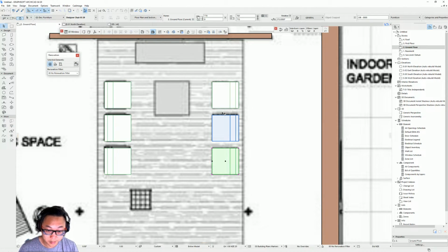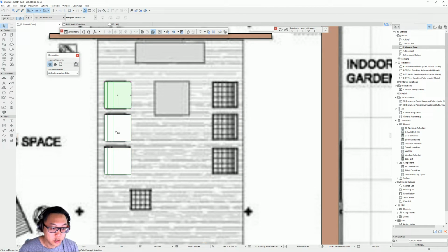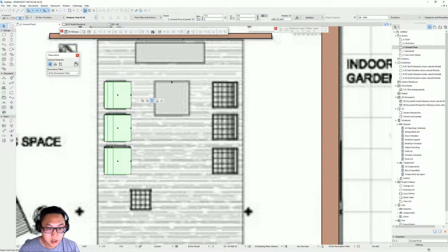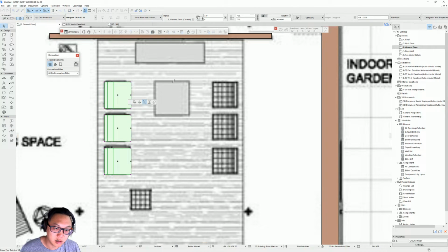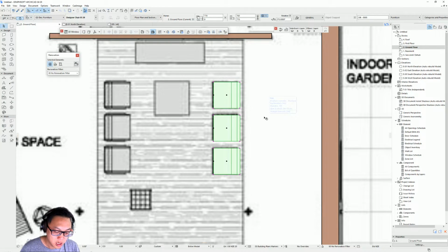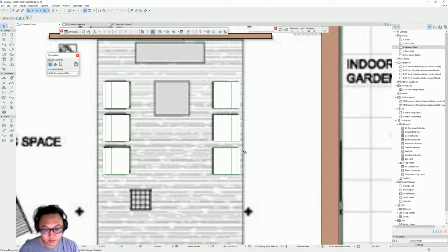The easiest way is actually you delete those, you select all the elements here, click on one point, and just use the mirror tool. And actually we have to place that table because the mirror tool is like I'll show you. Just press here, set the axis of the mirror, and now it flips on the other side. But then you want to actually have a copy, so I forgot to press Control. So you go mirror tool, select the axis. As you can see, there's no plus sign. So if I press Control, there's gonna have one plus sign. Now there's another copy on the other side.